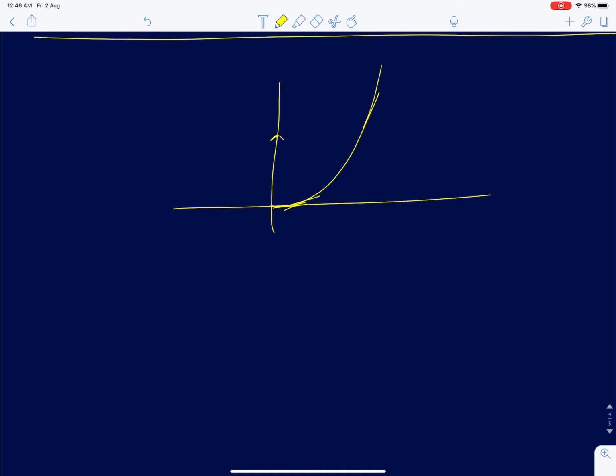Again, our model should not contain anything other than resistors and voltage sources. Of course, there is an ideal diode, which is a zero cut-in voltage diode. We can use that in the model along with some voltage sources and resistors. Then we should be able to somehow capture the effect of varying on-state resistance as the current increases.